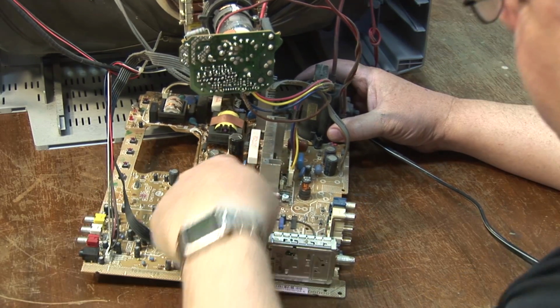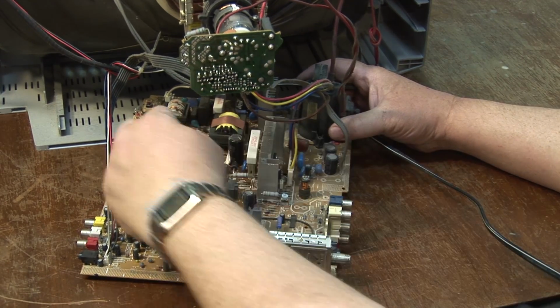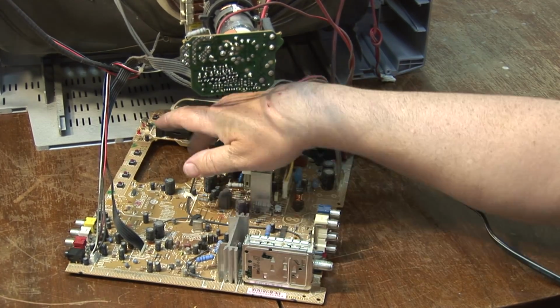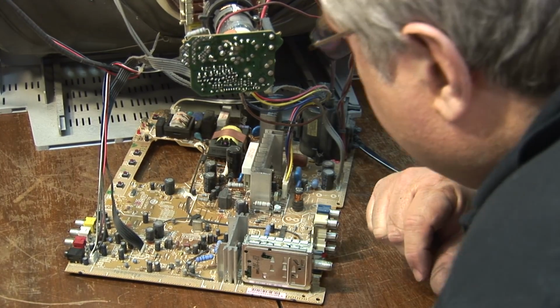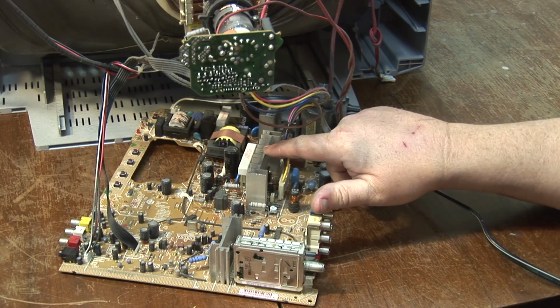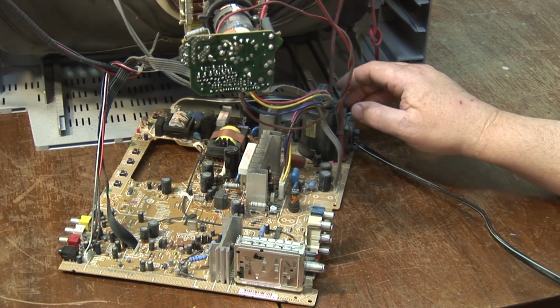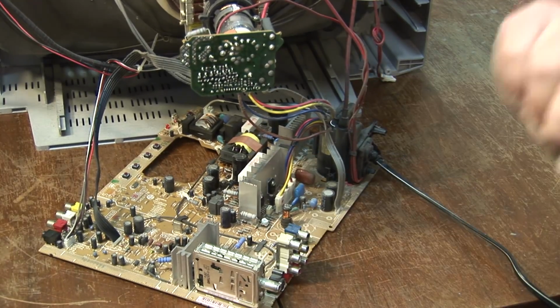Okay, we have some diodes down here. This is in the power supply. This is one of our main diodes in our power supply here. These are our rectifier diodes from our switching power supply. And this transistor down here, I haven't looked at it yet, but it is more than likely our horizontal output. This one here that's mounted alongside the vertical output IC on this big heat sink.